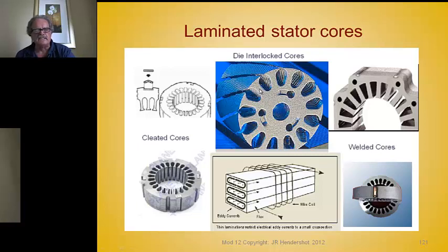And they even are able to skew these stacks. In other words, they have servos that will rotate the notching station, or the dimpling station, so that when it puts these together, it gives you a natural skewed stack.